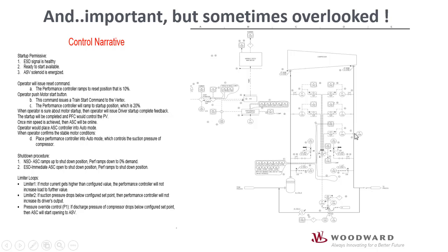Now you can also figure out the number of heat exchangers, or whether the heat exchanger is after the anti-surge valve or before the anti-surge valve. Preferably, we want the heat exchanger after the anti-surge valve.